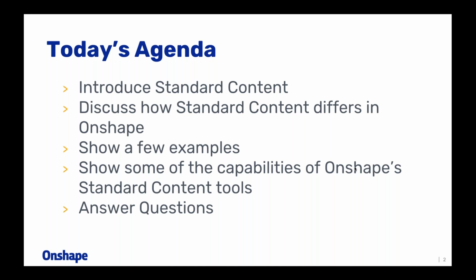If you haven't inserted standard content yet, I'll walk you through how to insert it, all the little details of using it, how to insert things very quickly, how to adjust where things are in the bolt stack and so on. We're going to go through some of the more advanced capabilities of standard content as well. We'll start simple with just inserting a simple bolt. But then we'll get into how do I populate an entire face? How do I insert washers between the bolt and the nut, and all those types of things.